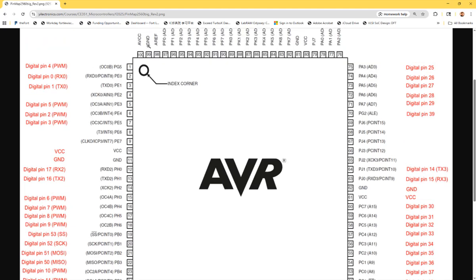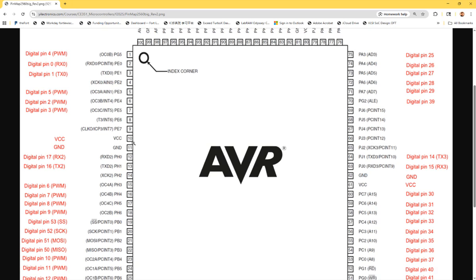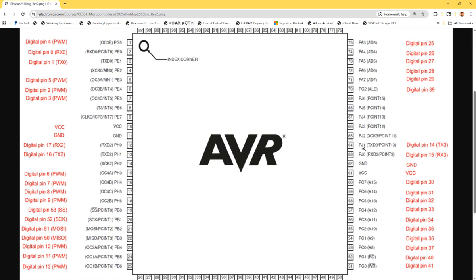If you look at the pins of the microcontroller, 100 pins, and they all have their names. The ports include D ports, J ports, H ports, A ports, like PA. But for other very simple microcontrollers, you won't see H and J, because usually they only have 28, 30-something pins. Usually B, C, D, and that's it. Not even E ports, because every port has 8 pins, usually from port 0 to port 7, because in an 8-bit microcontroller all the memory banks are 8 bits. For this one, it's different because there are so many pins, so it goes up to H and J and all these. So I understand what's going on.